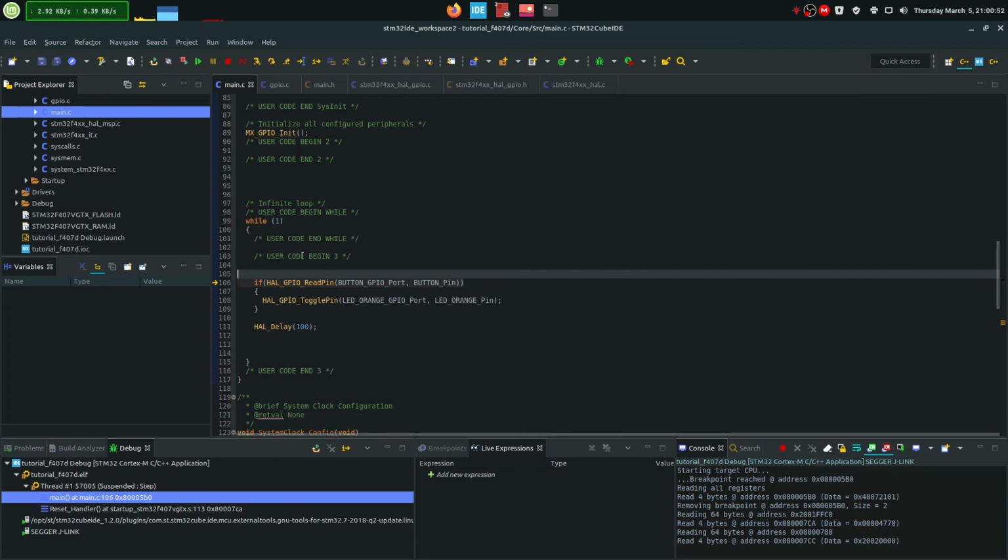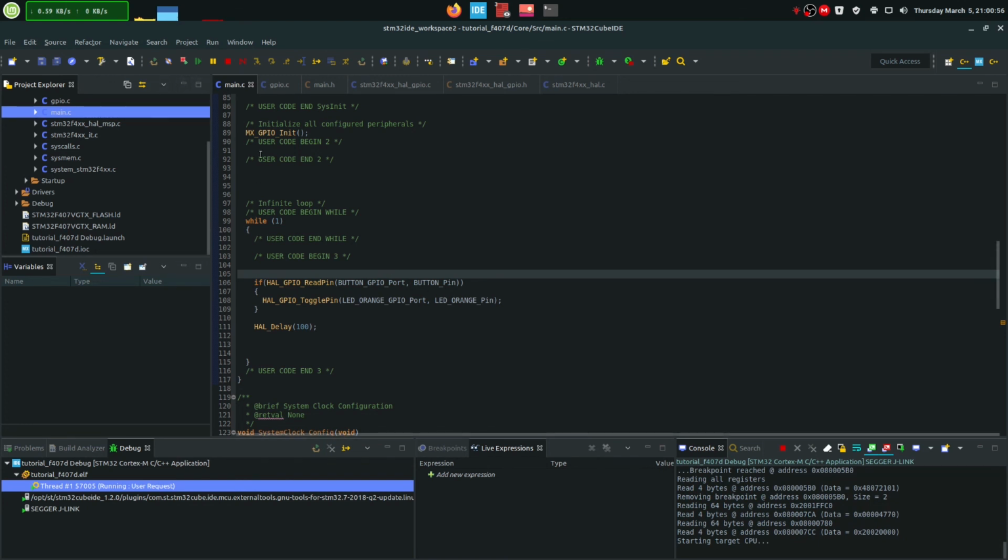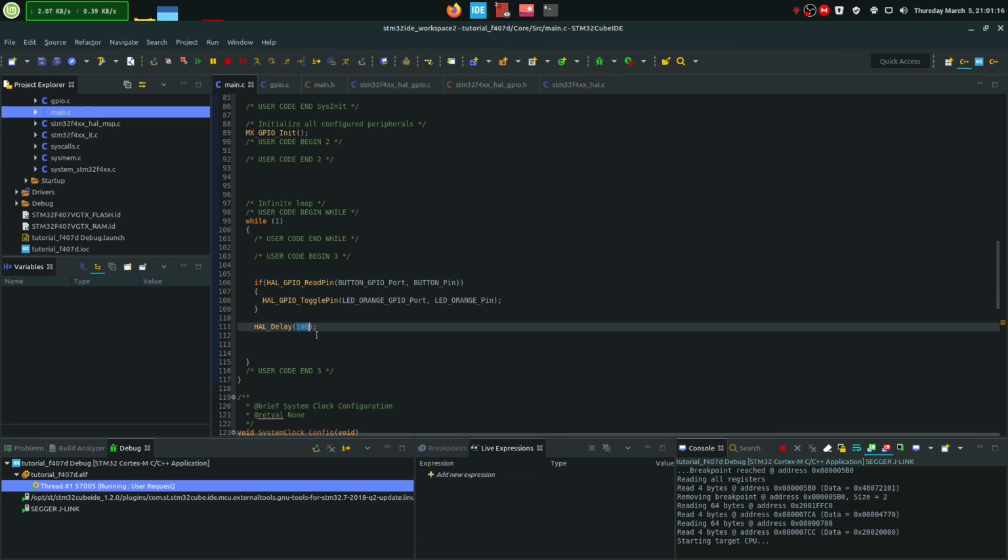The next part is, does it do this? So let's run this code, F8, so the code is running, no LEDs are turned on, and if I click the button fast, whoop, it turned on and off, turned on, oh, you have to be really fast. It turns on and off, and if I hold it, it just flashes rapidly, and it flashes 5 times a second, because in case we have a period of 100 milliseconds, every 100 milliseconds it toggles. So on and off, it's 200 milliseconds, so 5 times a second it turns the LED on and turns it off.